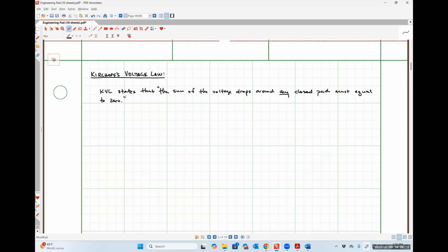So we learned in our last class meeting that voltage is the work done per unit charge to move 1 coulomb of charge between 2 points in our circuit, okay? So KVL saying that the sum of the voltage drops is really related to the sum of the energy transferred as we push our charge around. So KVL is literally nothing more than the law of conservation of energy in circuit form, okay? It can never be violated.